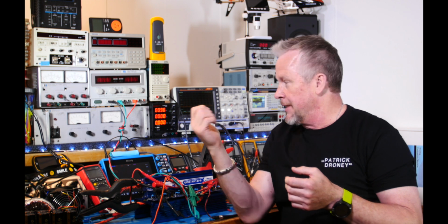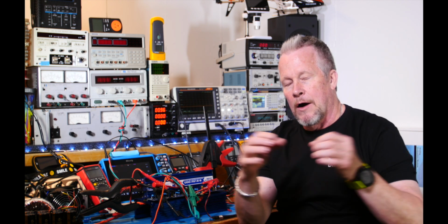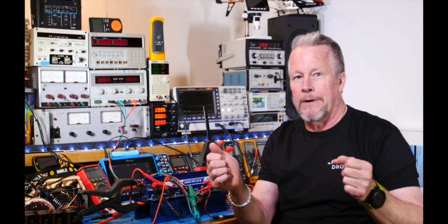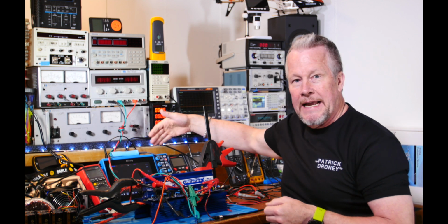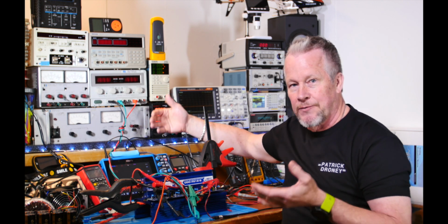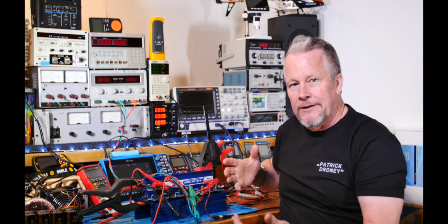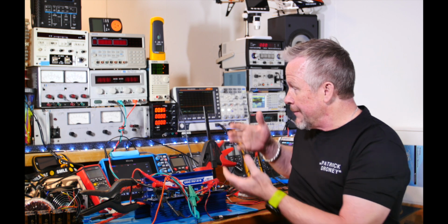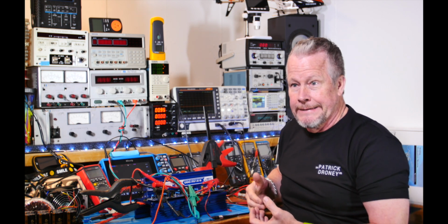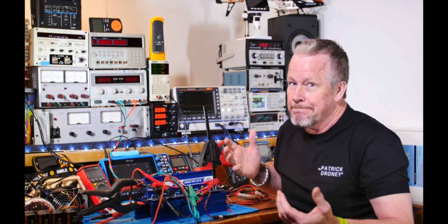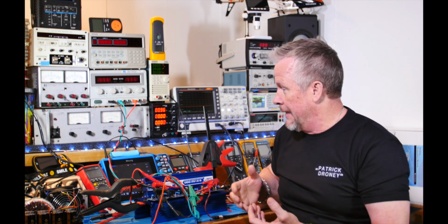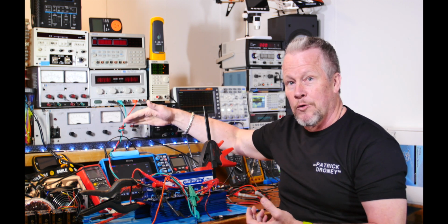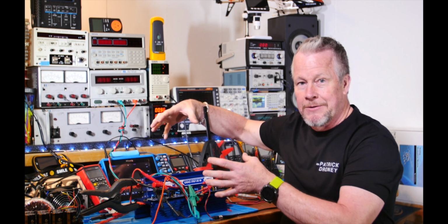But still, you have 4 channels on this mixed sig. All 4 channels, the grounds, the BNCs are tied together, right? So the metal, you can actually touch them, so that could be dangerous if that was floating. If I'm looking at, say, a tube amplifier at 300 volts, or some high voltage, and I'm floating my scope for that reason, some people do that. People float scopes, and if you're doing that kind of stuff, you've got to be very aware of that, because those BNCs will be floating at whatever potential they're tied to.